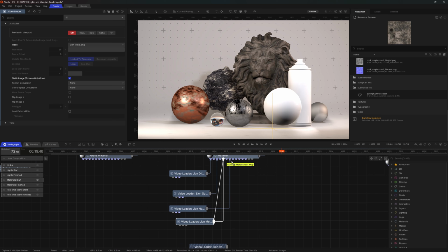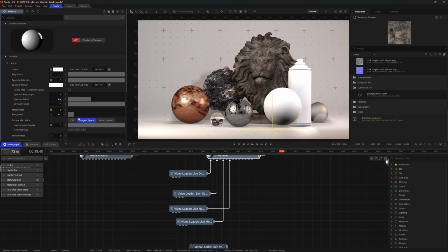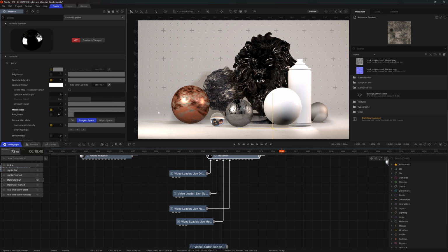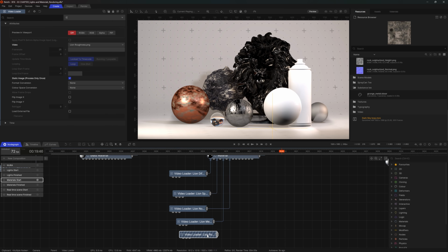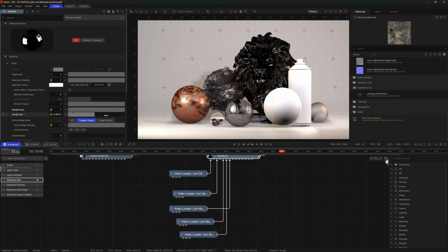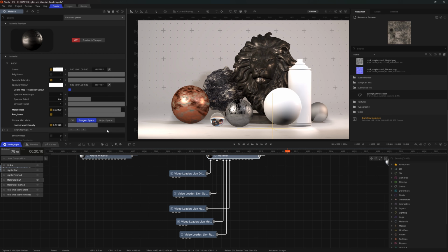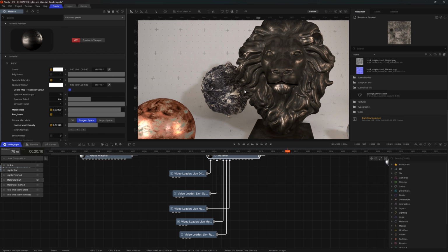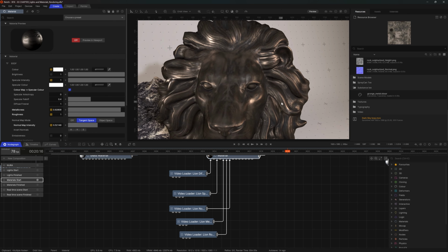So for this to properly kick in, we probably will need to go into the material and slide the metallicness property on. Fantastic. And now we have roughness. Let's add that in too. Emissiveness, roughness. So this too needs to be enabled. There we are. And just like before, we do want color map to pick specular color. Maybe a tiniest bit less metalness. And maybe a little bit less of normal intensity. Yeah, I'm quite happy with this material here.